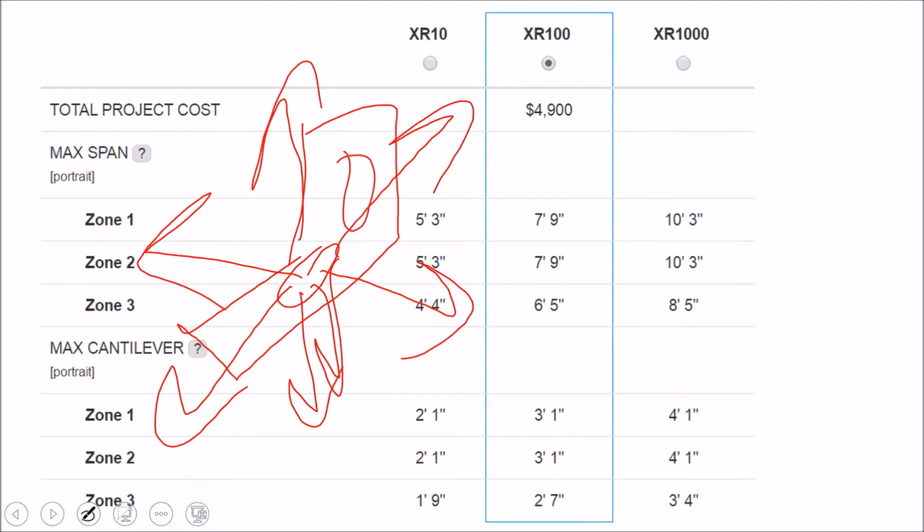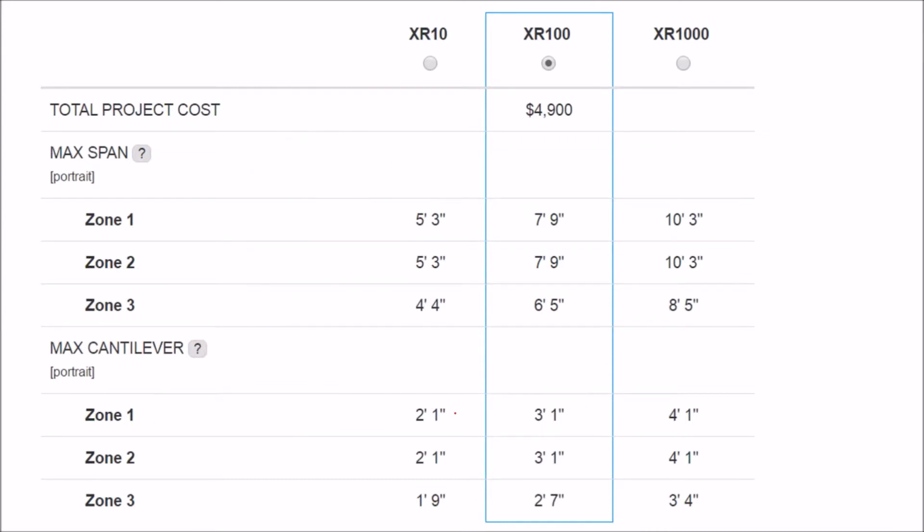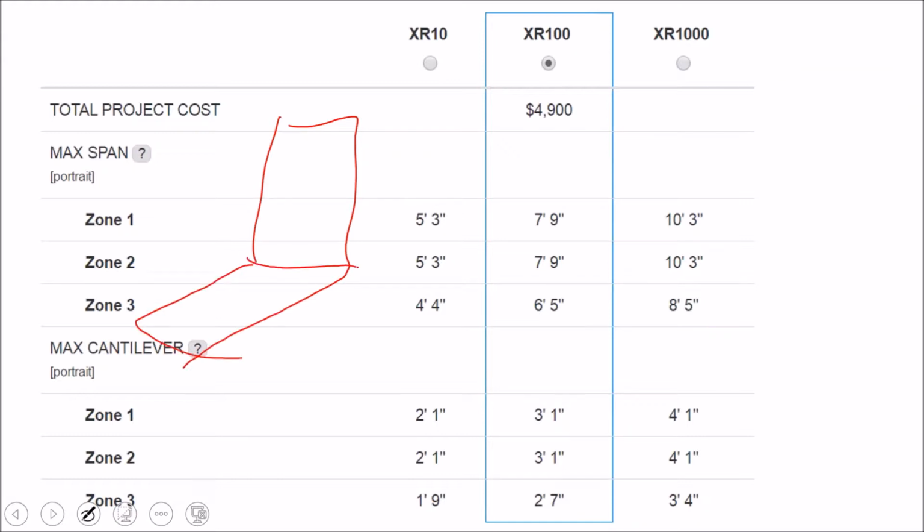Over 10 years, 20 years, the wind is picking the array up and slamming it back down and vibrating it back and forth. So is it the attachment that causes the leak? If so, there's not much you can do about that other than not do the project. Or is it the force on the attachment that causes it to leak? And how do you reduce that force?